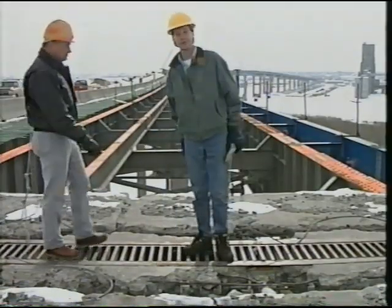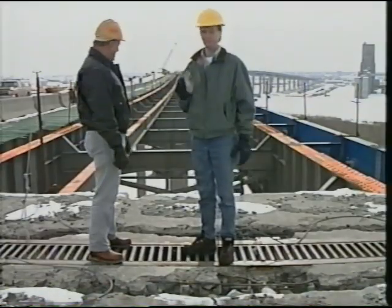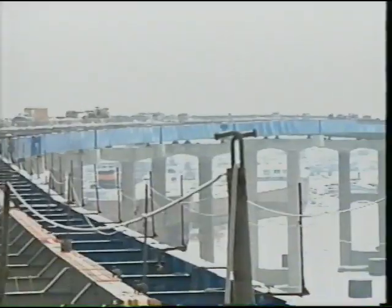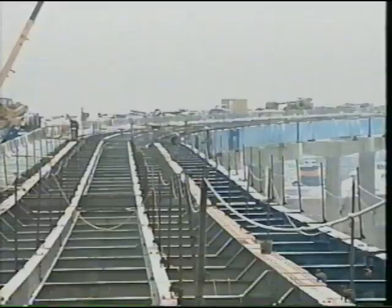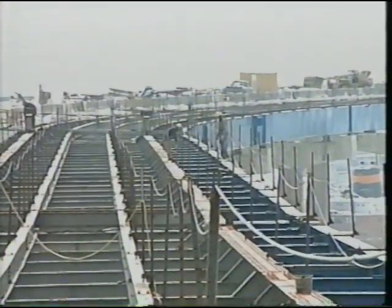As you can see, this is where the old deck stops, and the new renovation starts. That's right, Howard. This bridge has a lot of the same parts as the Phoenix Bridge. We have 2 main girders, with floor beams every 30 feet to support the stringers. We have a new girder on the outside that allows us to put a deck over the entire area and have an 8-foot safety shoulder on the outside.